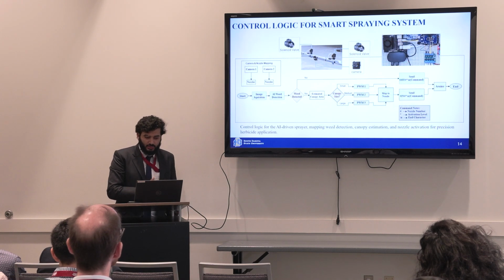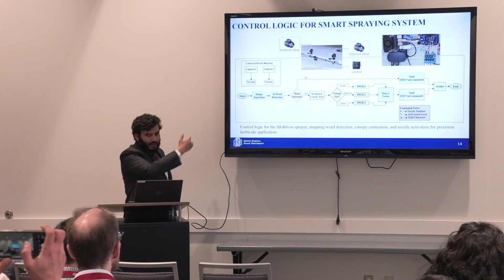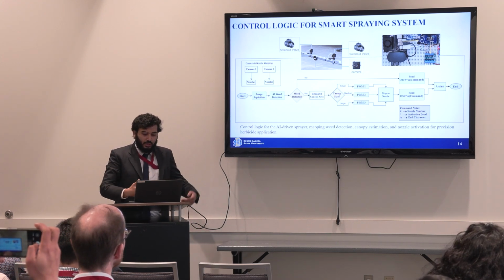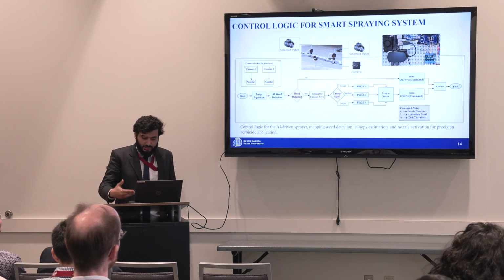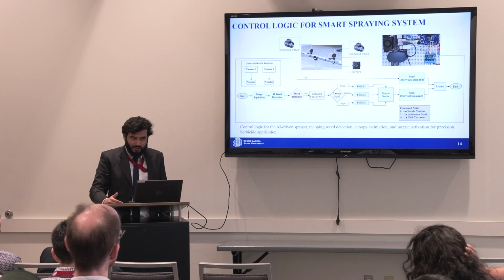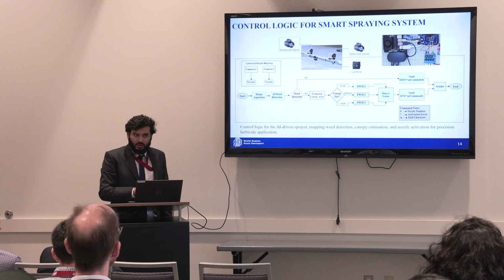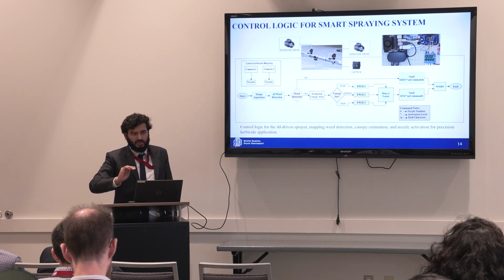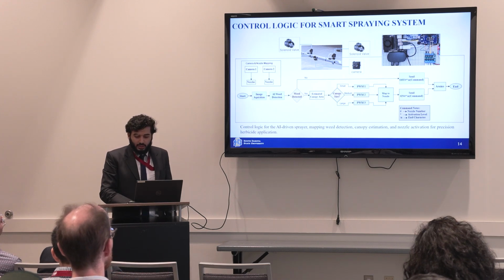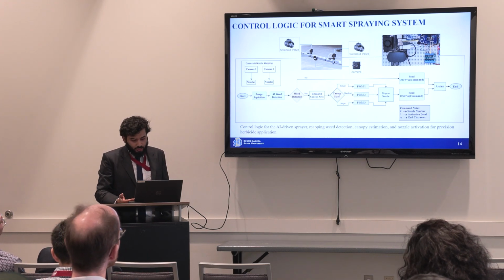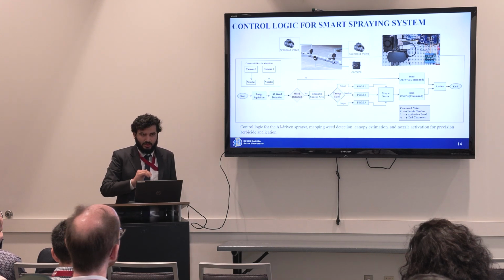This is the control logic. As I told earlier, we have our camera and 2 solenoid valves in the middle, and first of all, image acquisition takes place. The AI detection model runs to detect whether we have weed or not, and then a decision is made at this stage in real time. If you don't have weed, a string is sent serially from the NVIDIA Jetson to the Arduino Mega. OFF pound \n means turn off that nozzle.